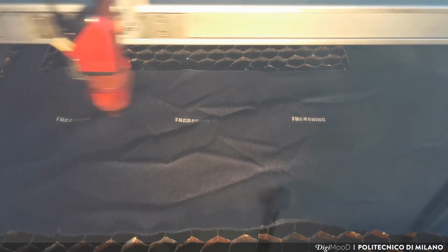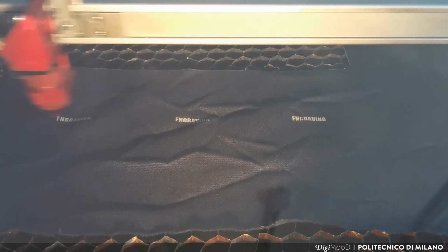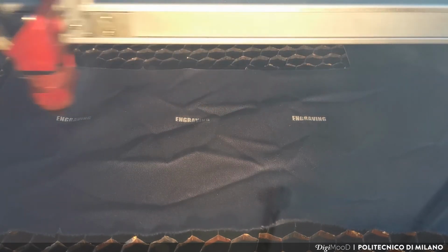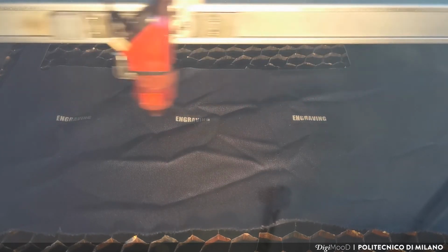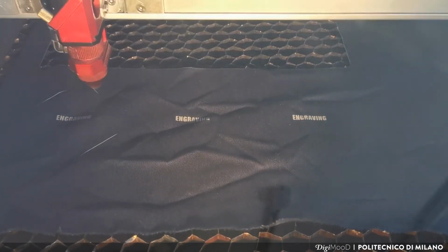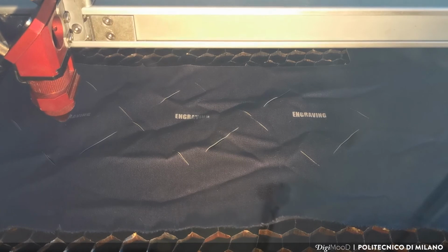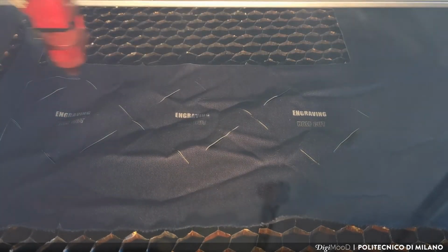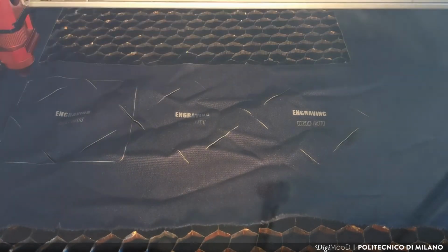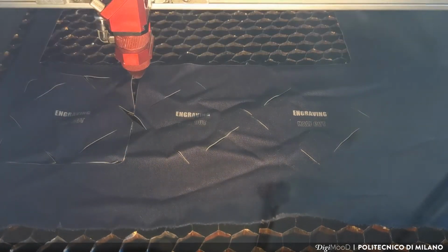As you can see, the engraving operation takes more time and consequently has a higher production cost, because the machine follows a raster logic. Meanwhile, when the machine performs the vector cutting operation, it is evident that its efficiency increases. However, some thicker fabrics may require more steps to achieve a precise cut.